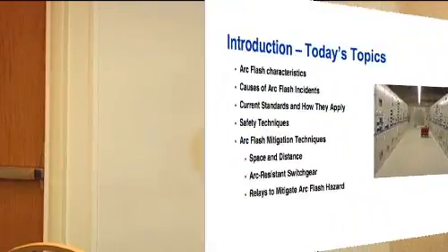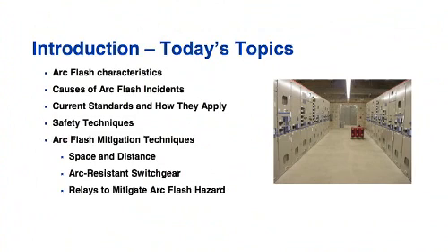Today's topic is arc flash and the mitigation techniques involved in it, causes of arc flash, the current standards, the safety techniques that I'd like to see y'all follow, arc flash mitigation, which includes the space and distance, which is the 1584 standards, the arc-resistant switchgear, which obviously we make, and different types of relays, primarily the optical relay, which is the REA.